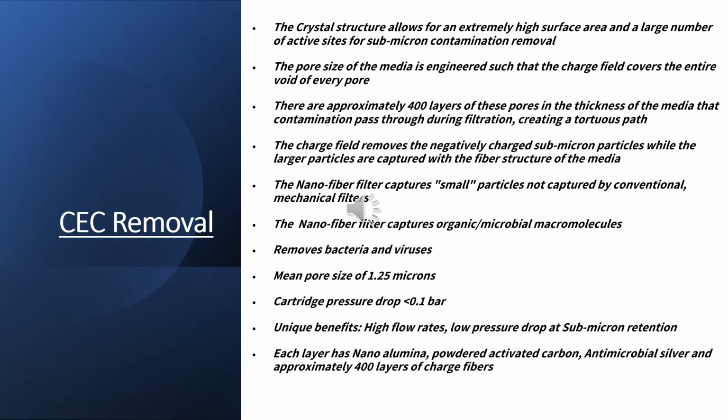Still on CEC removal, the crystal structure allows extremely high surface area and a large number of active sites for submicron contamination removal. The pore size of the media is engineered such that the charge field covers the entire void of every pore. There are approximately 400 layers of these pores in the thickness of the media that contamination passes through during filtration, creating a tortuous path.